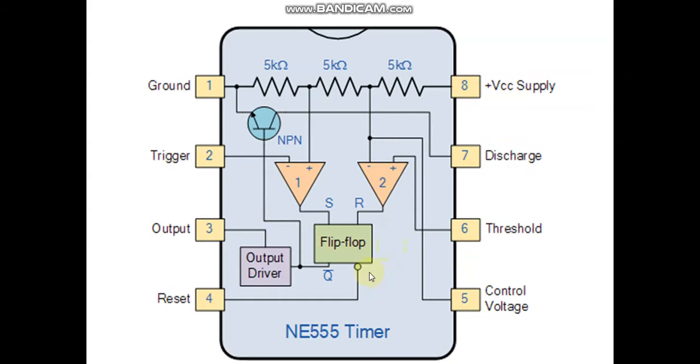The internal block diagram is being given, and with this IC you can have a variety of output waveforms with the addition of an external RC circuit. The 555 timer chip is extremely robust, and it is a stable 8-pin device that can be operated either as a very accurate monostable, bistable or astable multivibrator to produce a variety of applications.